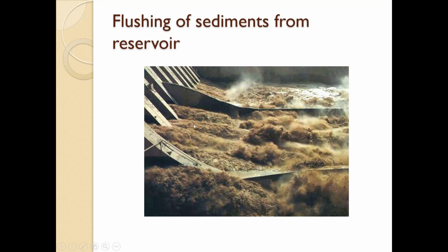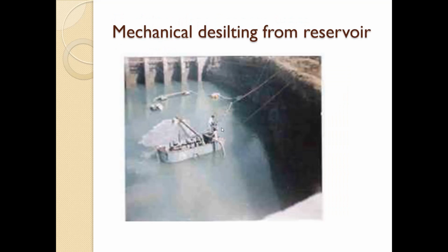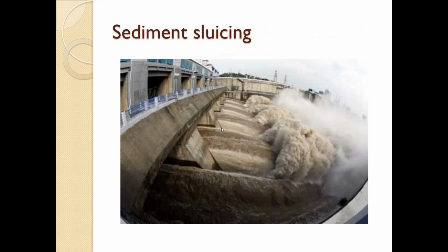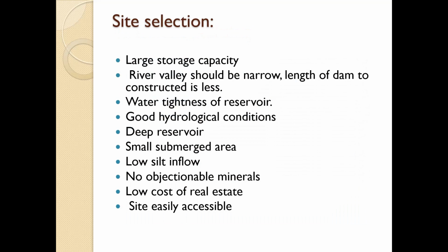Then this is the flushing of sediment from the reservoir. So you can see from the bottom, the debris and all the silt-contained water has been discharged. And this is the mechanical desilting of the reservoir, so the silt can be sucked and thrown out from the reservoir. This is sediment sluicing.